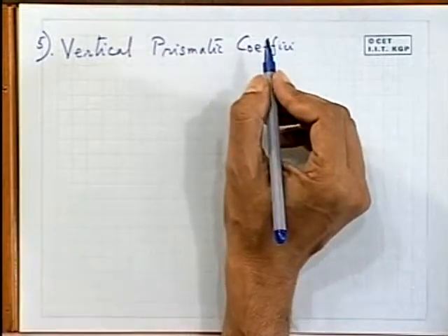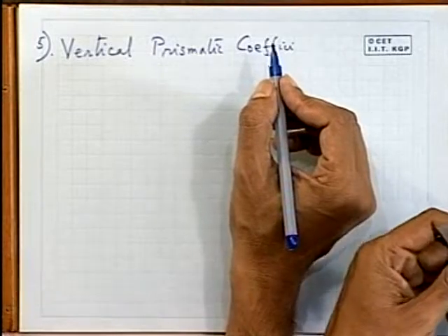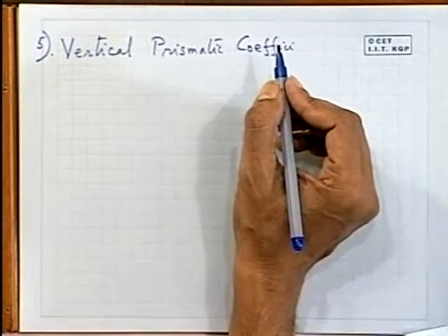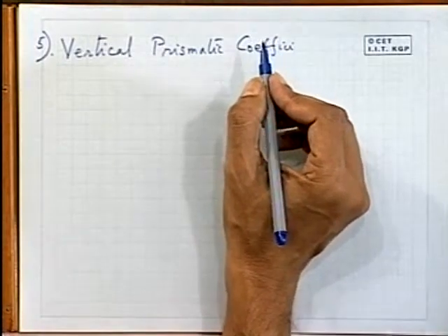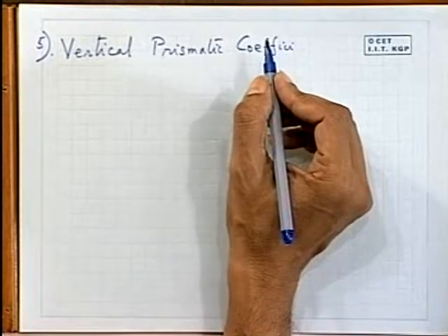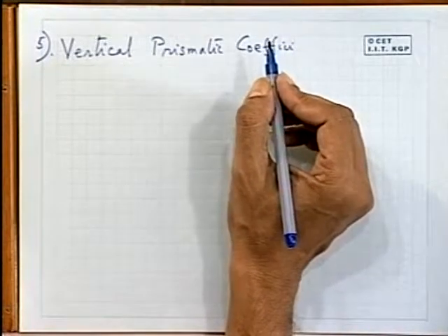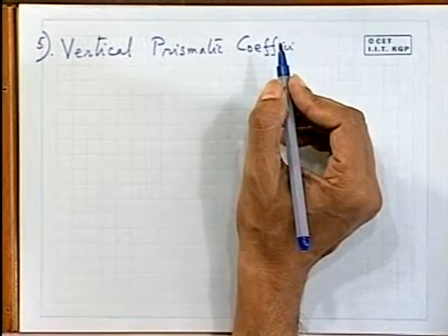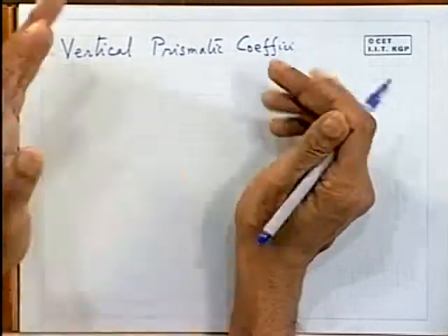Normally the Cp that we have calculated is taken along the longitudinal dimension of the ship, that is, immersed area multiplied by the prism. Prism means what? A solid object having uniform cross section area. Prism can be rectangular, can be square, or the sides can be a polygon. The vertical sides can be a polygon, but in between there should not be any change in shape.